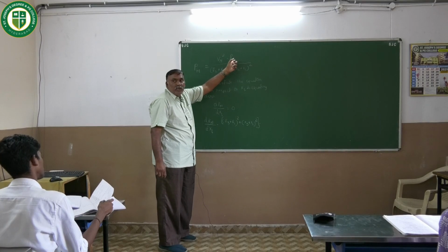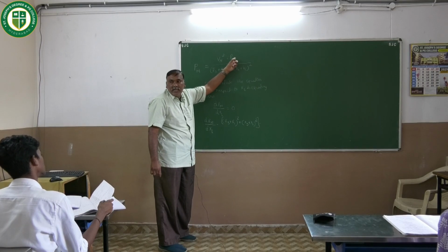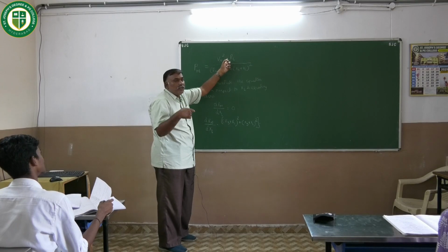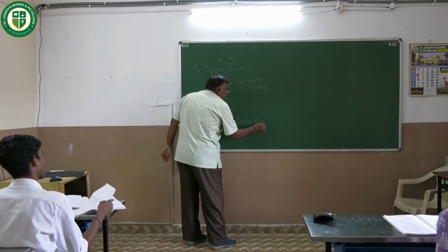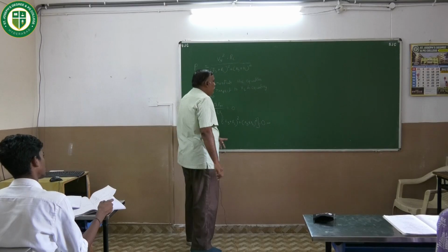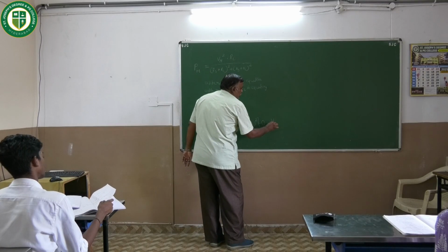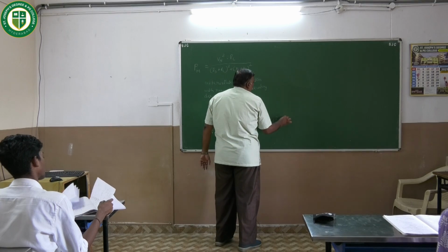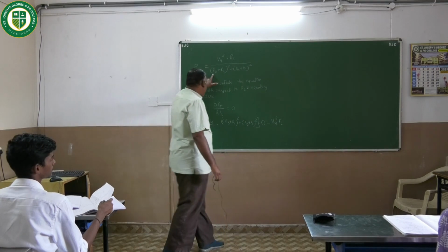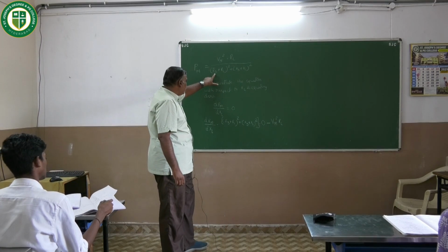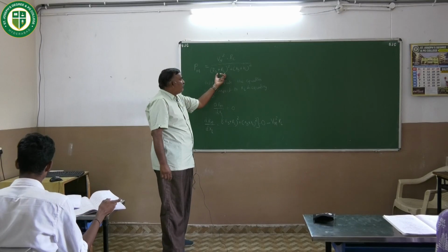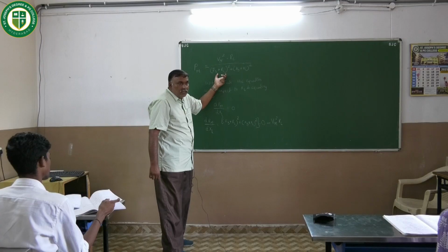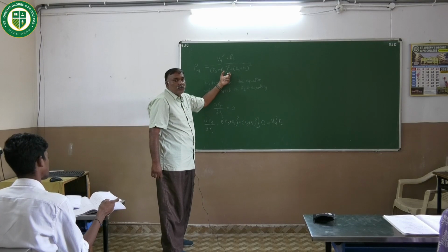It is in the form of uv. RL is constant and Vm is also constant. Differentiation of a constant is going to be 0. So it is 0 minus u into v dash, so it is going to be Vm square into RL into v dash. If I differentiate with respect to XL, the first term is going to become 0. Am I right, class? Because (Rs plus RL) whole square is a constant.